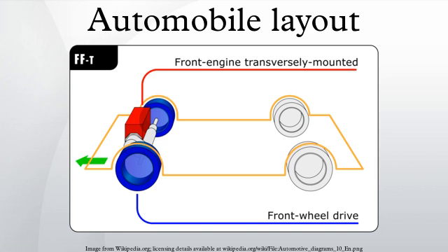Disadvantages. 4WD systems require more machinery and complex transmission components, and so increase the manufacturing cost of the vehicle and complexity of maintenance procedures and repairs compared to 2WD designs. 4WD systems increase powertrain mass, rotational inertia and power transmission losses, resulting in a reduction in performance in ideal dry conditions and increased fuel consumption compared to 2WD designs.